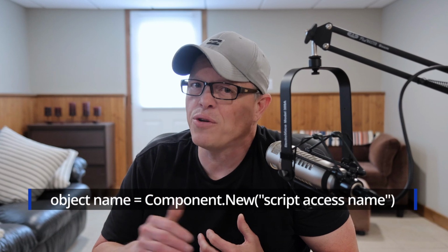The Component.New command technically creates a new object. This new object can reference any block that we've given a scripting name to in our Qsys program. We will use the scripting names that we assign to the NV32 and the LG device driver blocks. These new objects can then be used to change various elements within those blocks. Here's the format for the Component.New command.